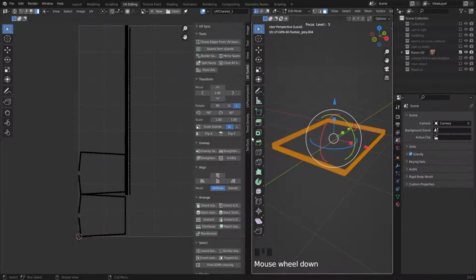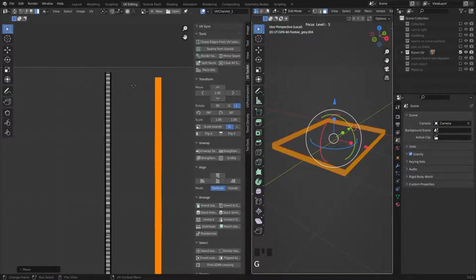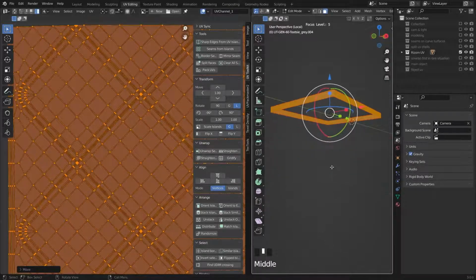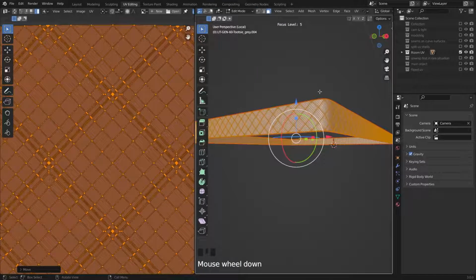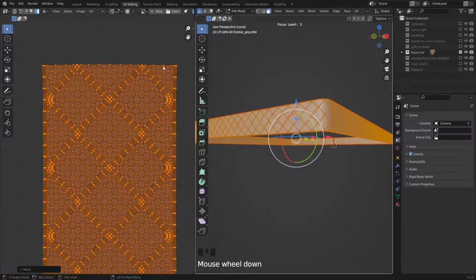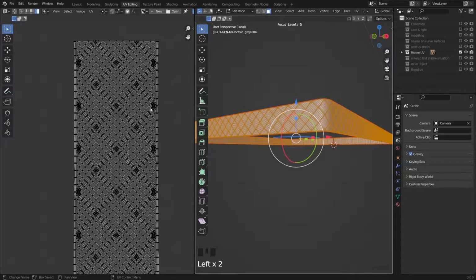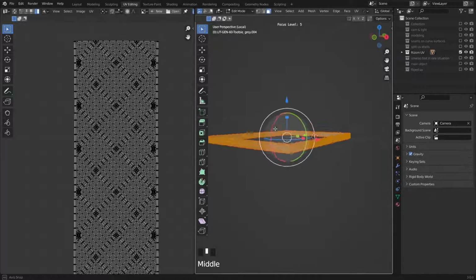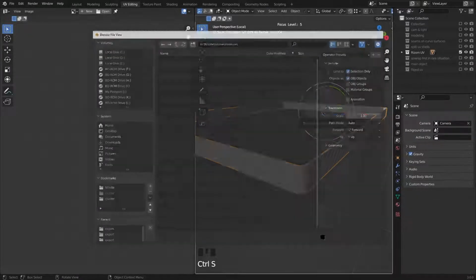Okay, as you can see, Blender unwraps the object, and I want to talk about this part. You can see here, and if I zoom in, it's this front part. We should make the border edges completely straight. If I want to do that in Blender, it really takes time. So I bring my object to Rizom UV and unwrap it there. I export this object as an OBJ. I put it here, export.